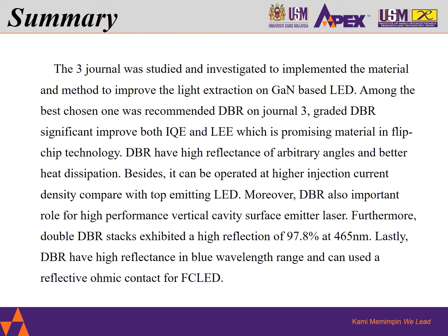DBR has high reflectance at arbitrary angles and better heat dissipation. Besides, it can be operated at higher injection current density compared with top emitting LED. Moreover, DBR is also important for the role in high performance vertical cavity surface emitting lasers. Furthermore, the double DBR stack exhibits a high reflection of 97.8% at 465 nanometer. Lastly, DBR has high reflectance in the blue wave range and can be used as a reflecting ohmic contact for flip chip LED.